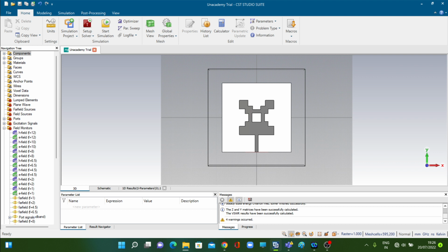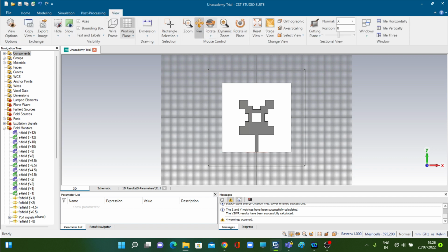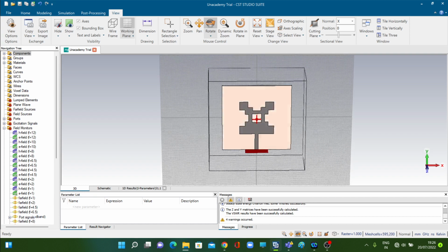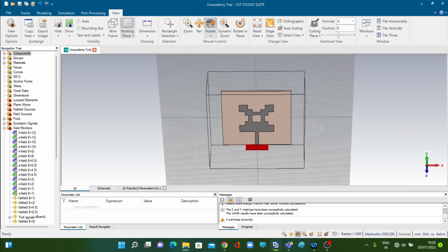So suppose this is the antenna structure which we already have designed. I will just rotate it in plane a bit. See, the waveguide port is also seen like this, which will serve as the connector, the interface between the actual feed line, the antenna, the entry, the gateway of the antenna, and the coaxial cable which will be on this side. So this waveguide port serves as the gateway for that transition region of the antenna.